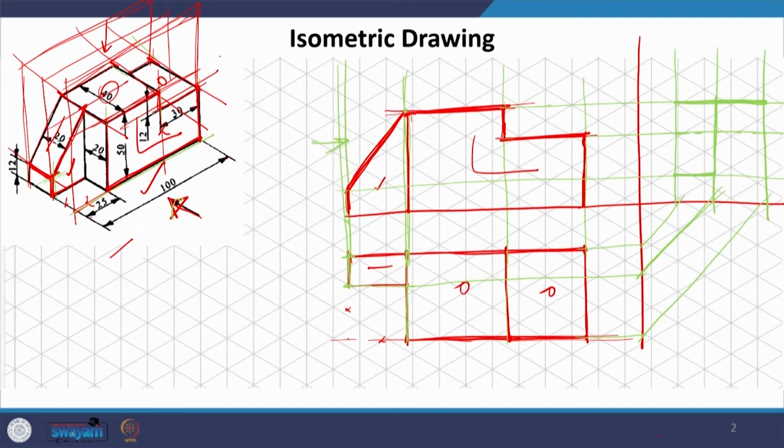Straight, there is nothing, if you look at it from this side, there is nothing which is interrupting this. So, we have this line here, but this line remains absent because this is the line which we were seeing in the top and not in the bottom fully. So, we are only having this line here in the bottom at this level. So, if I darken it again, this complete thing is what we are going to get as our side view, and there will be a dotted line, because we are seeing the side elevation from this side. So, now you can verify again.